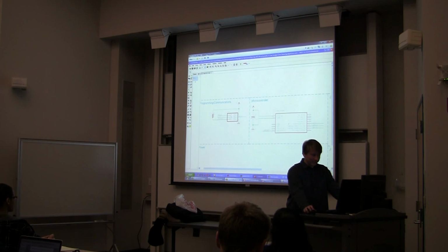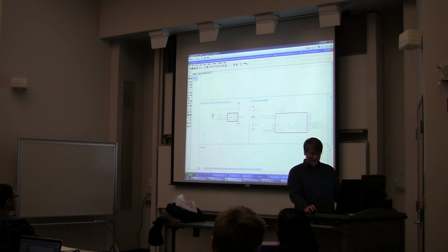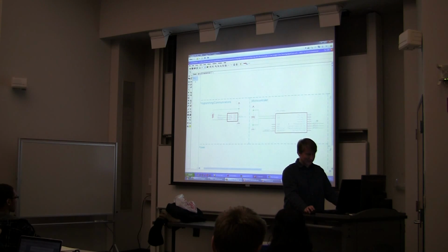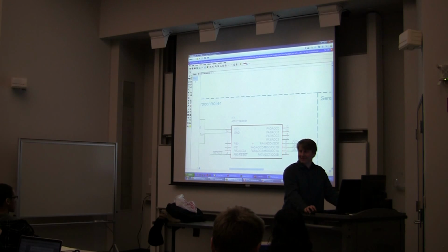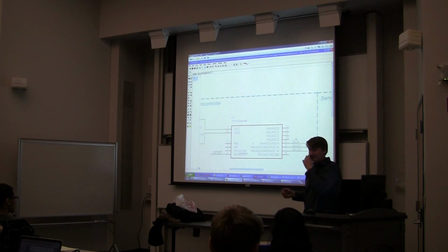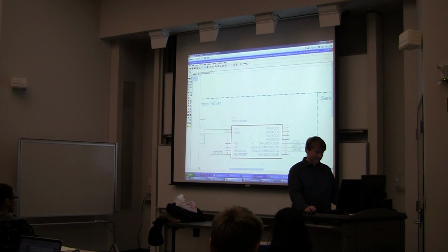So you want to make really sure that as you work on your gadget, you don't delete this, change the nets around, or put reset to some different pin. So you want to avoid deleting these. When you're actually using your gadget, you are allowed to use these three pins and connect them to something else. It's just when you're programming, something funny is going to happen.